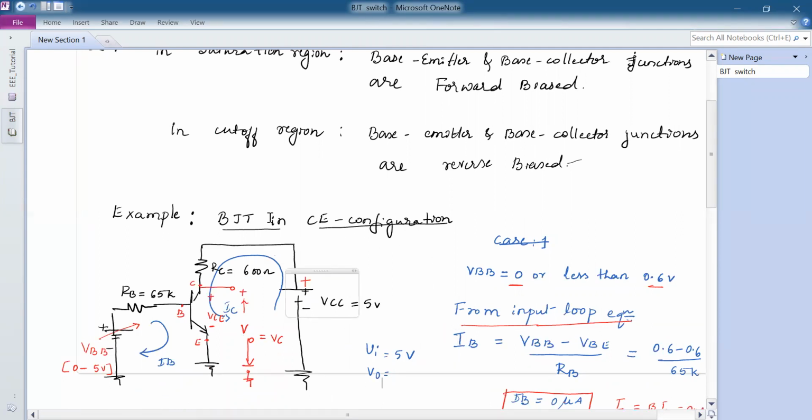Let us understand what components are connected in this circuit. Basically, an NPN transistor is considered in this example, biased in fixed bias mode where the emitter is directly connected to ground. You have a base resistor RB and a collector resistor RC.